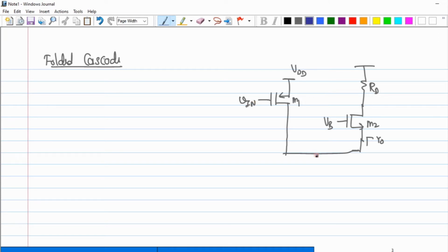I will not make you think too much. I'll just put a tail current, IS. The value of this IS comes from two transistors, right? The DC current that flows here is a summation of the current that flows through M1 and the current that flows through M2, because there is a potential difference from VDD to ground in both parts. So I have current in both paths, and they add up to create this IS. Now this circuit is properly biased because the currents are flowing. Clear?